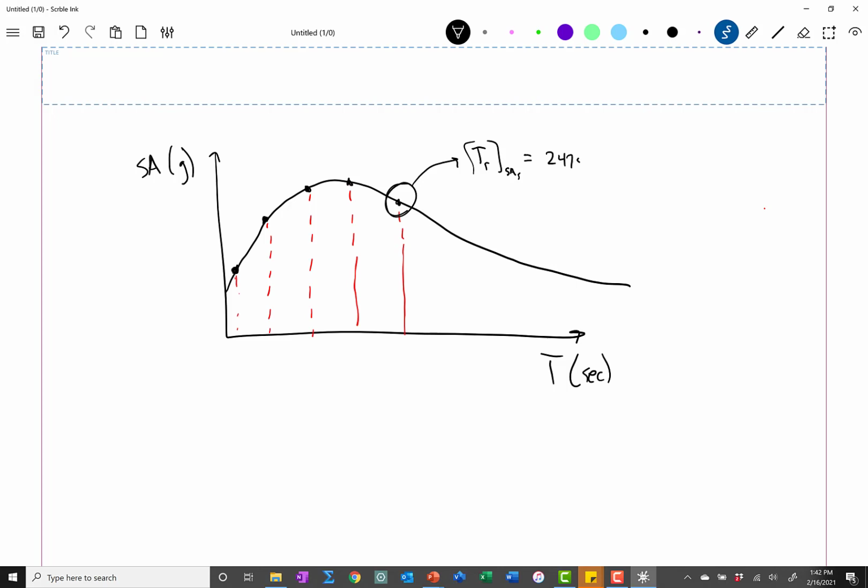It might be 2475 years. It could be something else. I'm just using that number. And in this case, the return period of spectral acceleration 4 is the same likelihood. And this is spectral acceleration 3, so the return period of spectral acceleration 3 is 2475 years, on and on and on. And so every point on that response spectrum corresponds to the exact same return period.